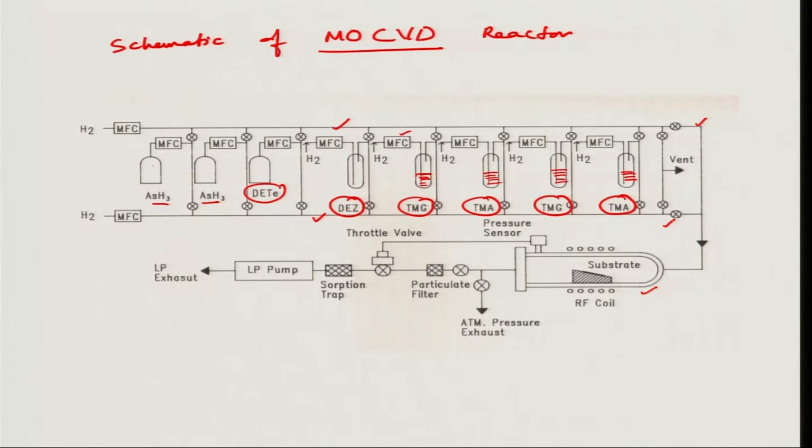It is required because these are used to control the composition in the thin film. So, these are used to grow your light emitting diodes, solar cells, okay, quantum well structures, where suppose you are growing gallium arsenide, then for a very thin film you grow aluminum gallium arsenide, then you again grow gallium arsenide, then probably you will want to grow indium gallium arsenide.